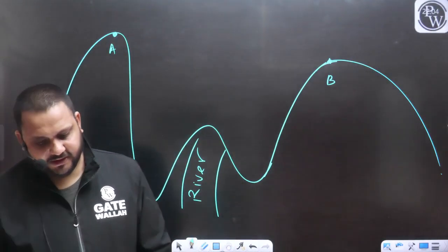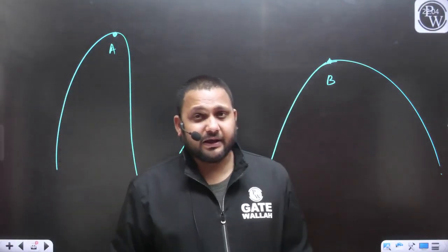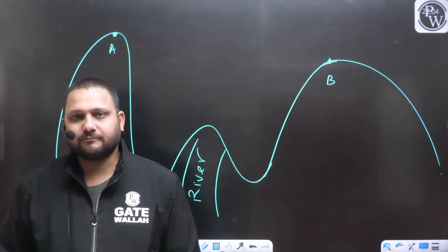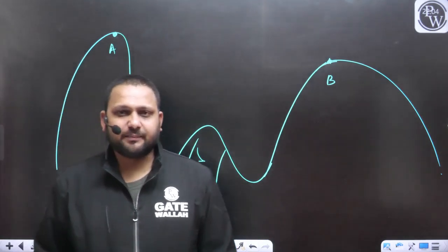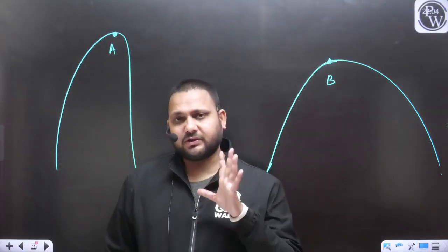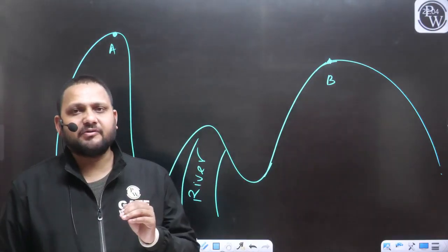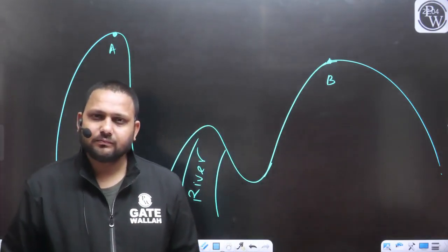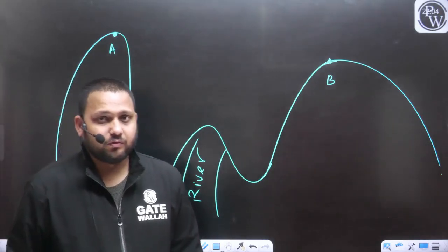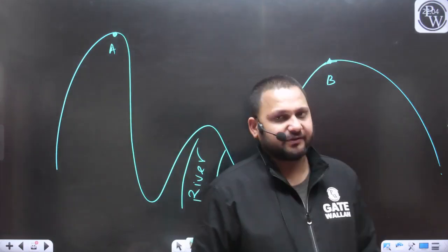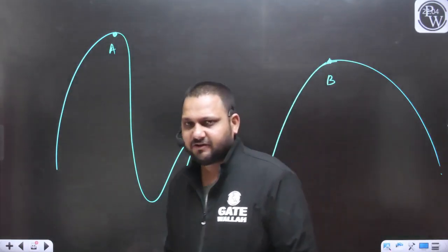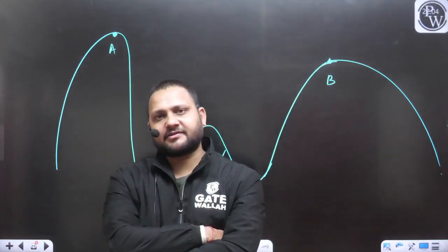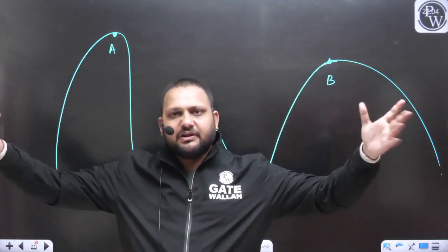Yes or no? And another important thing about reciprocal leveling. This is the advantage of reciprocal leveling. If we are going for reciprocal leveling work, there will be no requirement of the curvature and refraction correction. We will see how. But as of now, in the entire leveling work of reciprocal leveling, you need not apply any correction for the curvature or the refraction, no matter what the distance between the point A and B is.